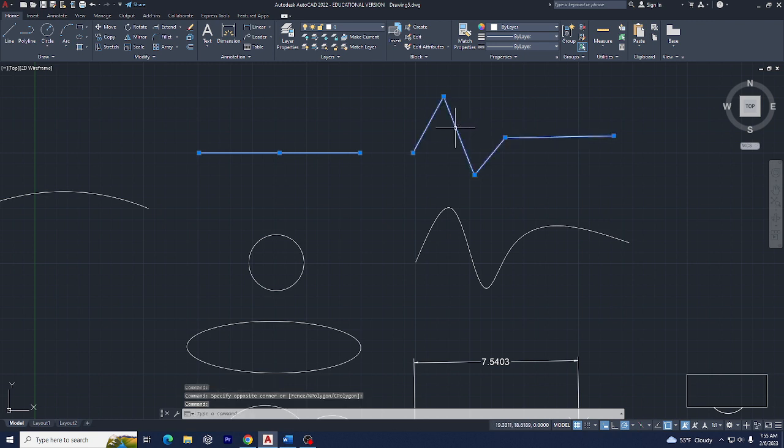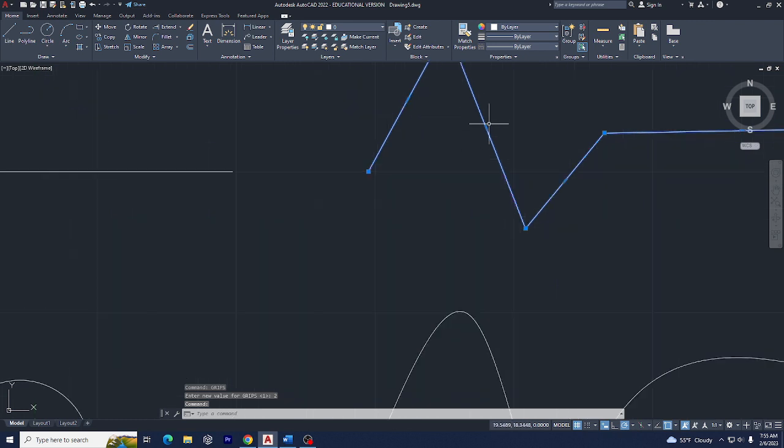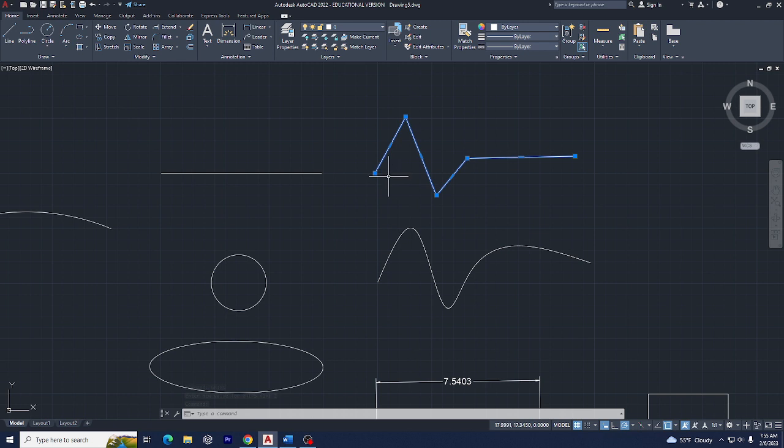Let's look at this polyline. Okay, you can see all those grips. If I do GRIPS again and enter 2, now you'll notice on the polyline these little dashes in between. We usually keep it on 2, but you can turn them off or have just the grips themselves on and not the centers of the grips.